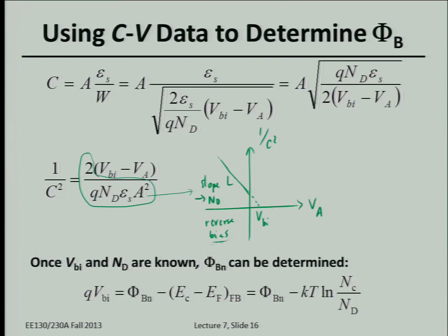And the reason why we only take measurements in reverse bias is because to measure the small signal capacitance, you have to measure the displacement current. Under forward bias, there's too much diode current flowing, and you won't be able to detect the displacement current. The displacement current is small, and your ammeter is only going to measure the total current. It doesn't care if it's displacement or DC. So basically, you want to make this capacitance measurement only when the DC current is small or negligible. So that's under reverse bias. So you make this measurement under reverse bias, so the primary current that flows is displacement current, not the diode current. That way you can get this kind of a plot and really figure out what your true